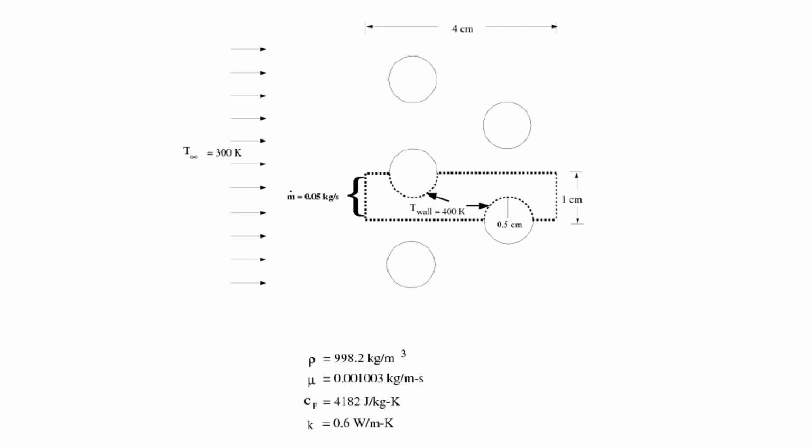We'll be working with a 2D section of a tube bank. The schematic diagram you're seeing right now represents the problem setup. The diagram you're looking at shows a bank of evenly spaced tubes, each with a diameter of 1 centimeter. The tubes are arranged in a staggered pattern across the fluid flow. The centers of the tubes are spaced 2 centimeters apart horizontally and 1 centimeter vertically. The depth of the bank is 1 meter.